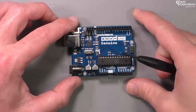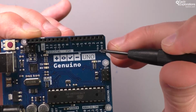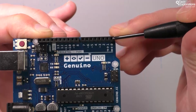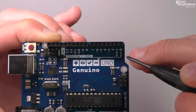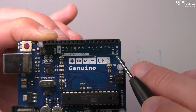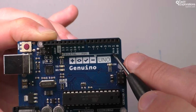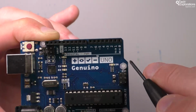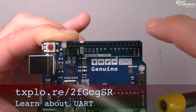So this is a functionality implemented on these 2 pins. These 2 pins implement one of the 3 serial communication protocols, the UART TTL, which is a very classic, very old communication protocol that allows you to transmit data and receive data at the same time. So it's a full duplex type of protocol.